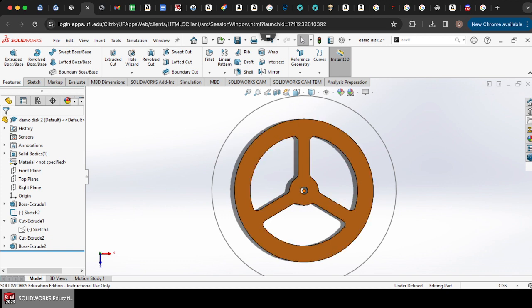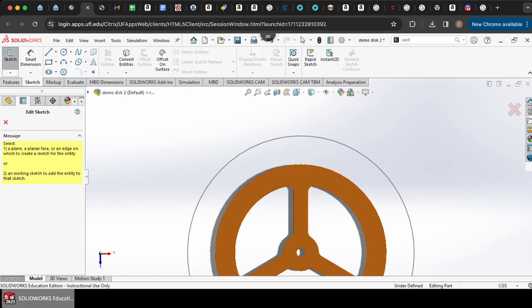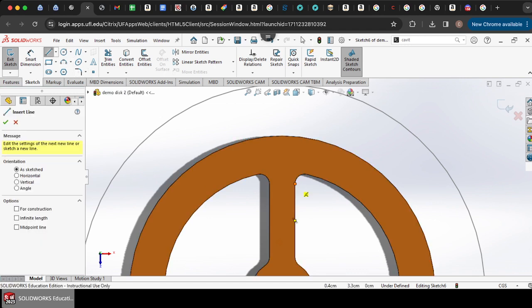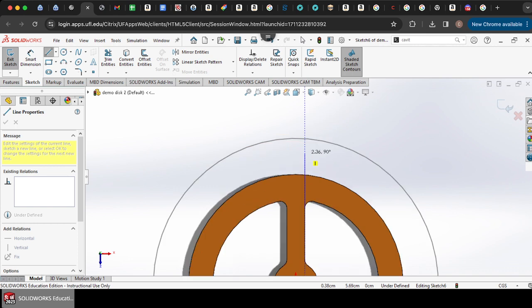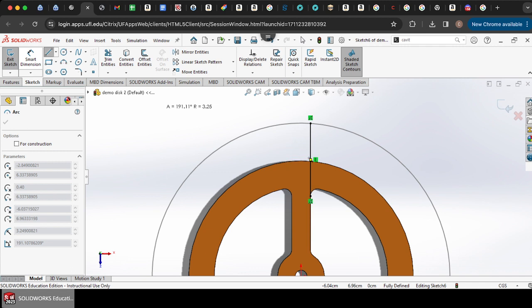You can see that's where you mount the motor. You have the outside of your disc, and then this is where your tooth would be. So on that note, let's go ahead and make our tooth. What I like personally is to start from where that center spoke is. As you have this thick bar coming up and merging into the tooth geometry, I like having that support there for the tooth. It's most definitely not necessary per se, but that's what I like.